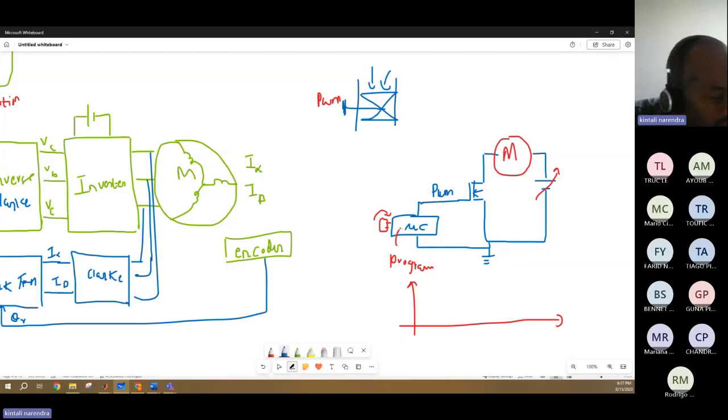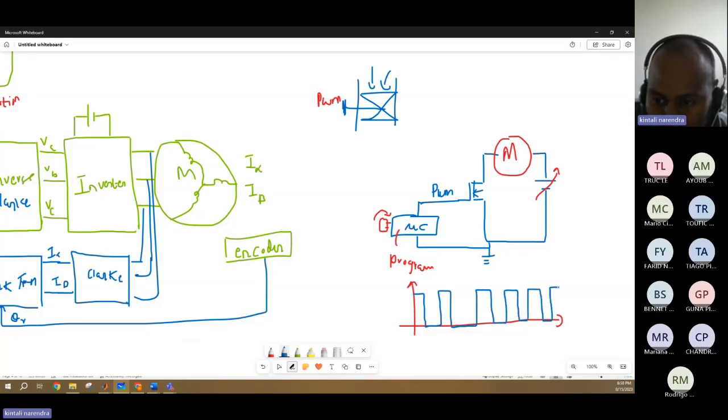At high frequency, a square wave signal will be coming out of this microcontroller, very high frequency. When you provide this signal, the average of the signal will be considered by the MOSFET. As you go from 0 to the highest rotation, in this experiment, if I change the knob position, then the width is changing. Otherwise, it is not.